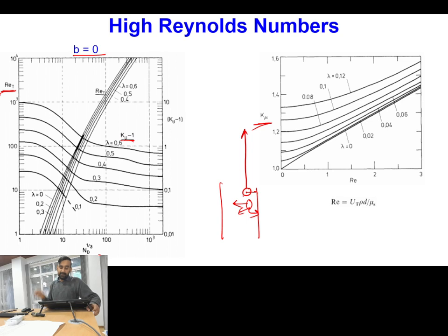Today we have majorly talked about this wall effect for particles which are spherical in shape, and I have specifically mentioned rigid particles. The meaning of rigid particle covers three situations: either a solid particle or a large K value particle, a fluid particle, or a contaminated fluid particle.